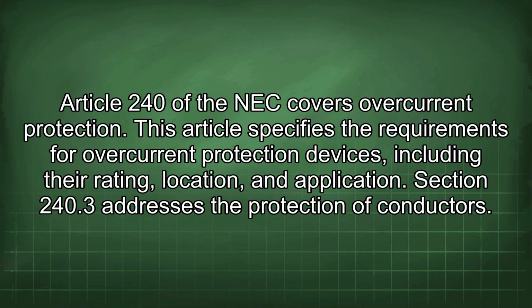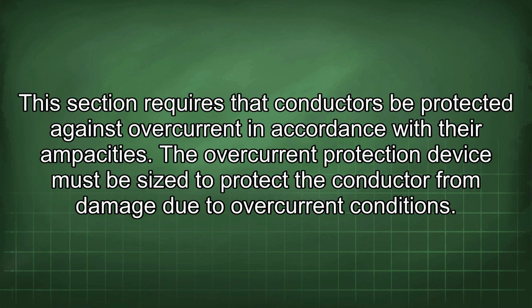Section 240.3 addresses the protection of conductors. This section requires that conductors be protected against overcurrent in accordance with their ampacities. The overcurrent protection device must be sized to protect the conductor from damage due to overcurrent conditions.